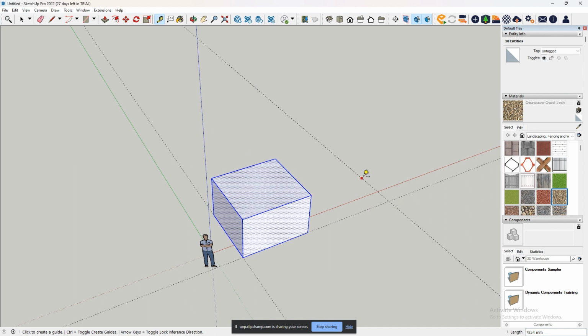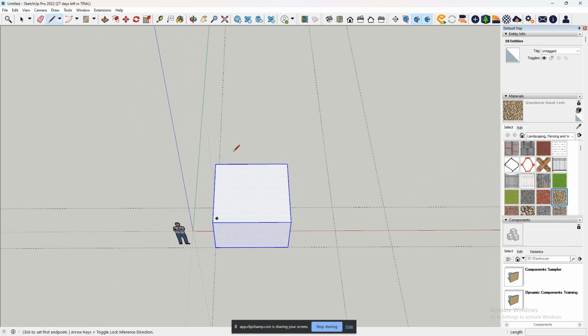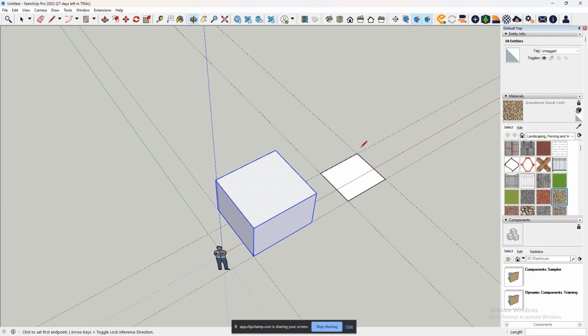And this is where you can start making grids, for example, and you can click it on the actual lines themselves, and then go to your drawing tool or any other tool you desire and highlight to where that little X pops up and it says intersection. Then you want to click on that, and this allows you to precisely get a shape based on measurements, little guidelines that you can prepare beforehand.